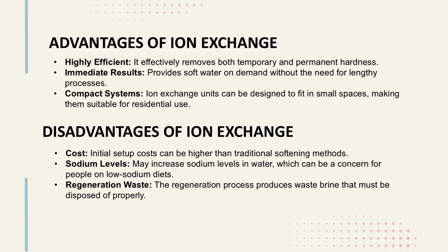The initial cost of setting up an ion exchange system can be higher than traditional methods. Sodium levels. This method increases sodium levels in the treated water, which can be a concern for individuals on low-sodium diets. Regeneration waste. The regeneration process produces waste brine, which must be disposed of properly.